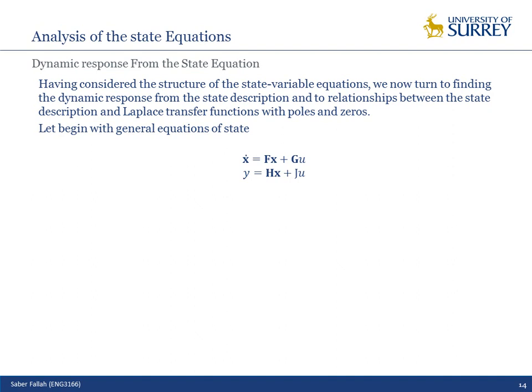First, what's the response of a first order system? What shape does it have? Exponential. Exactly. Very easily you can solve it. For example, if you have a third order system, you can solve it by this vector as an exponential response. But in order to solve this differential equation, I need to use the Laplace transform. If I take the Laplace transform of the first differential equation, I will have sX(s) minus x0, the initial condition, equal to FX(s) plus GU(s).